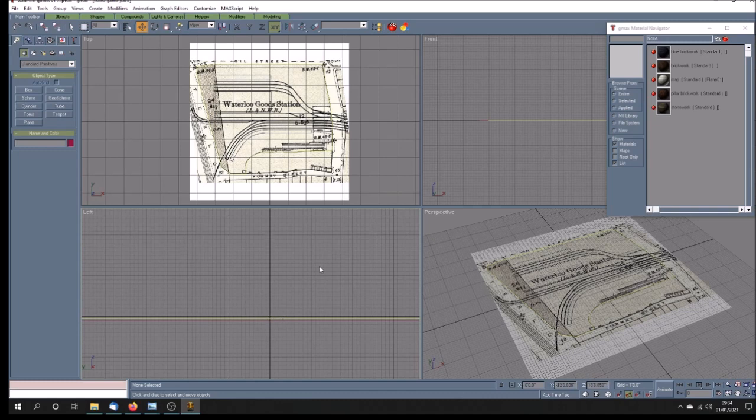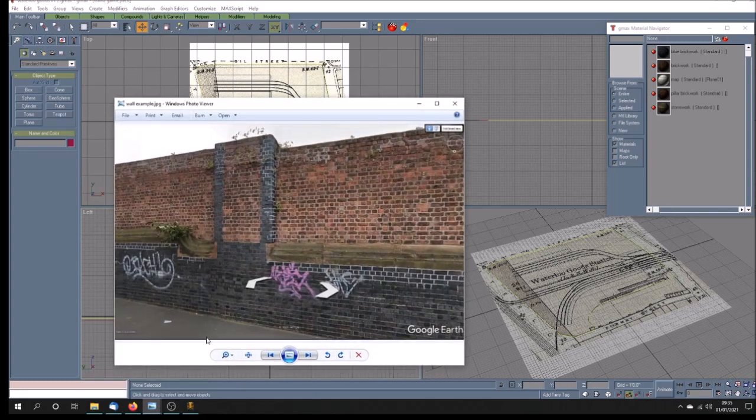Okay, so it's going to be 20 foot high, this wall. And if we look again at this, just keep reminding ourselves, counting brick courses and estimating the brick sizes, this height from about here to here, so this part, is about 4'6", and this is about another 1'3", and then I've got the same width for the stonework, and then we've got the pillar. And I'm just going to butt the stonework against it. So if I say 4'6" and 1'3", 5'9".